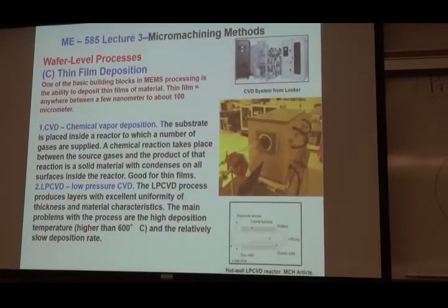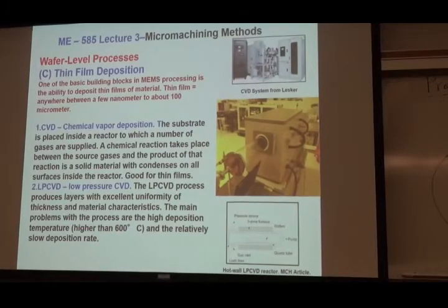What are the units on this concentration profile? Are you talking about the dopant itself? I was just wondering, how do you quantify this concentration profile? Is it just dopant per volume? Oh, yeah. Right. So, for example, to have an efficient N-type activity, to have excess of electrons, you could have 10 to the power N number of electrons excess.